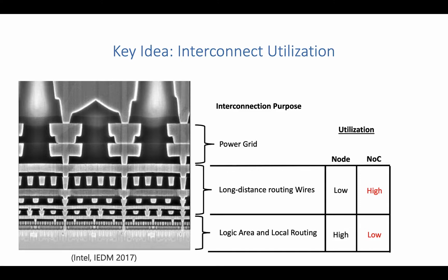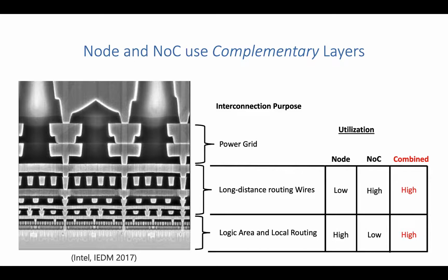Now, the key idea is that these two different pieces use complementary layers, so that if we combine the designs, if we combine the floor plans into a single symbiotic floor plan, we can get high utilization of the long-distance routing wires and high utilization of the logic area and local routing.